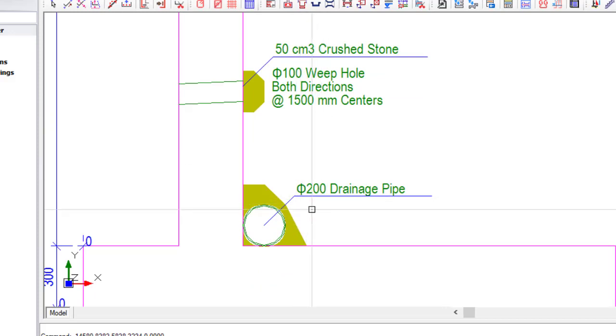And then this is the other drainage on the second side. We have two drainage systems, one in this direction and the other one in this direction facing me. So we use drainage pipe and we use whip hole for this. Whip hole is basically you are drilling a hole. You just put a pipe inside to make a hole while you are casting. So that is a natural pipe. Then this one is like an artificial pipe.